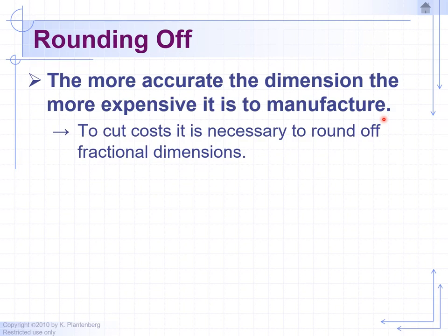If you're using 1 decimal place, like 1.0, then the machinist can go fast, machine the part at a high rate of speed, because accuracy is not important since you're only giving them 1 decimal place, such as 1.0. But if you're giving the machinist 1.000, 3 decimal places, then the machinist has to slow down and take their time to guarantee accuracy. So it'll drive the cost up.